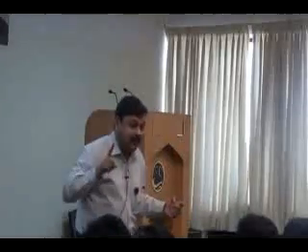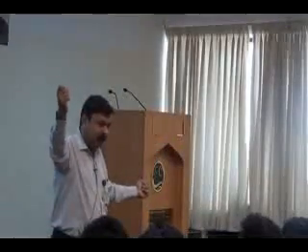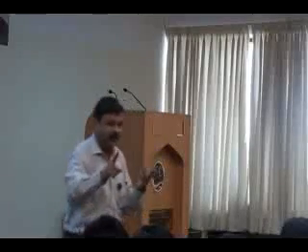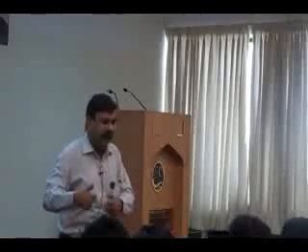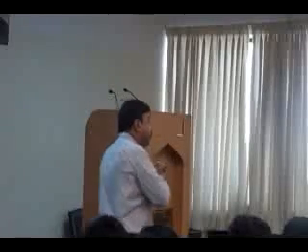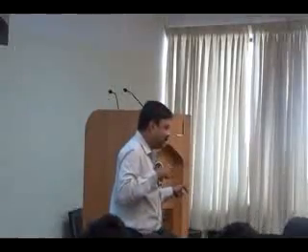So the increase in length is how much? 1 meter, because the original length is 1 meter. Original length is again 1 meter, that is unit strain. The stress that will produce unit strain is Young's modulus.